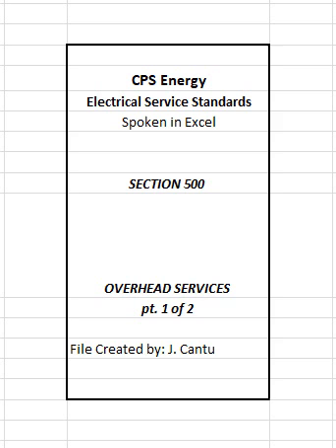503 Clearances on buildings from final span of service drop conductors. Where permanent attachment of service drop conductors to a building is necessary for connection to customers' service entrance conductors, the final span of service drop conductors shall be installed to meet the following requirements over or along the installation to which the conductors are attached.